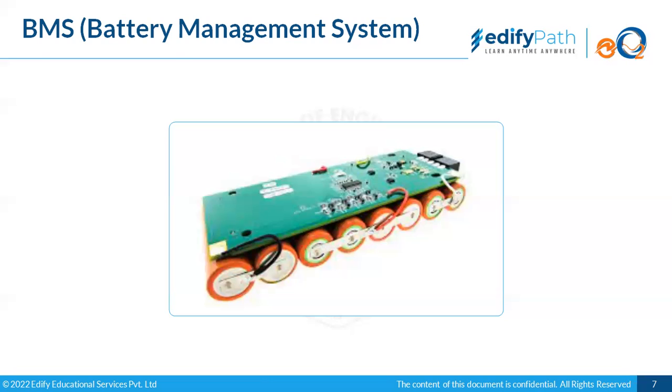Typically, BMSs are available in a certain amperage rating, and they also have an S rating, or series rating. The S rating signifies how many modules in series we can connect. If it is a 10S BMS, then at most we can connect 10 modules. A module can have n number of cells, but at most 10 modules can be connected in series through this BMS.